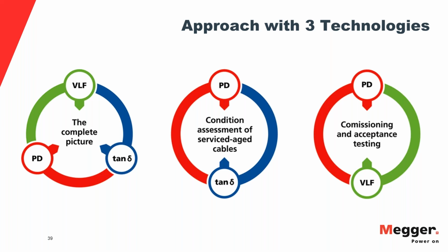And now here's the problem. In North America, it is very common that people have cables installed and they do not operate them at the maximum operating voltage that the cable could hold. Typical example, you have 25 kV cables in the ground, and because you want to satisfy some over-insulation recommendations, let's say at 133% or something, you use 25 kV cable and you operate it at 15 kV. Here it gets really, really complicated, which will be addressed in some of the other two parts.